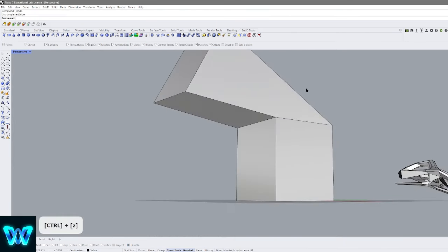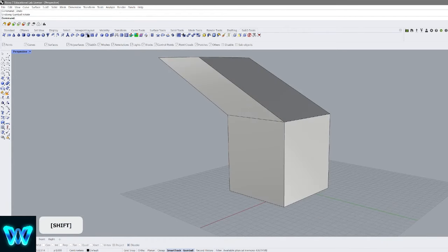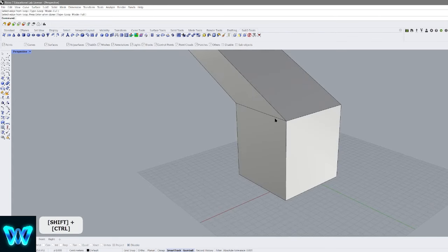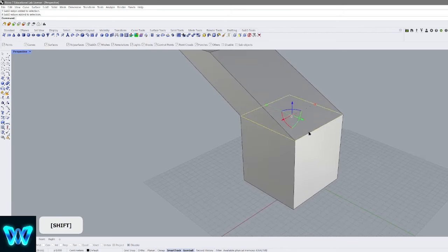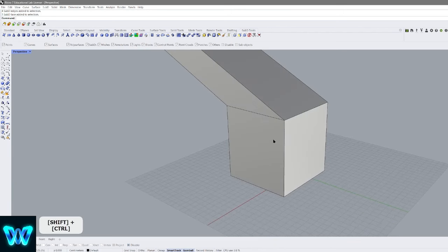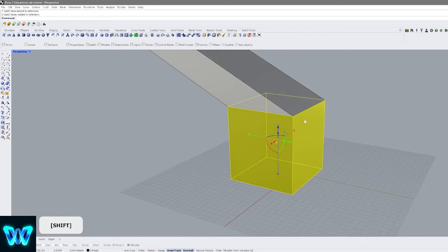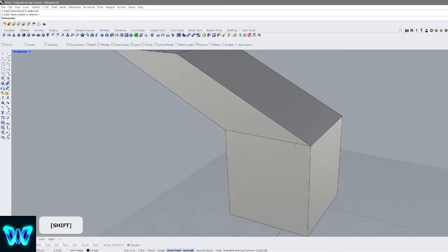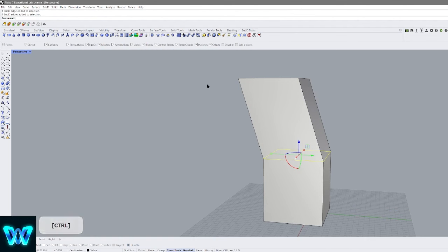At the same time, a faster way to select your edge loops, you can always just utilize the command and then you can select an edge loop. But instead of selecting just one edge, the moment you double click it, you select the whole edge loop. So if you click it once, just an edge, twice, edge loop. And same with faces. One, just the face, twice, you get a whole face loop. So the way the edge loop works, it works with edge loops and edge rings. So for example, let me make a couple edge loops here.